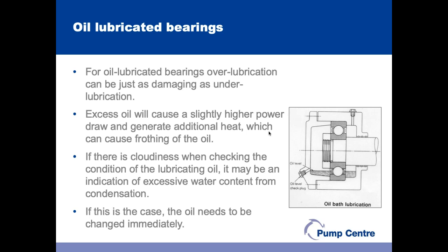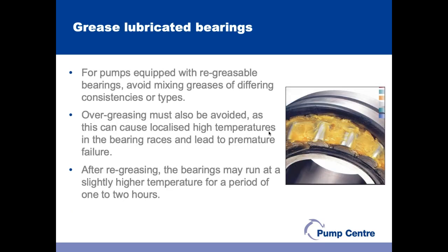If, when checking the condition of the oil, it looks cloudy, that may be because condensation has caused water to become mixed with the oil. That reduces the effectiveness of the oil as a lubricant, and in that case the oil needs to be changed immediately. When it comes to grease lubricated bearings, and of course many of the pumps out there have grease lubricated